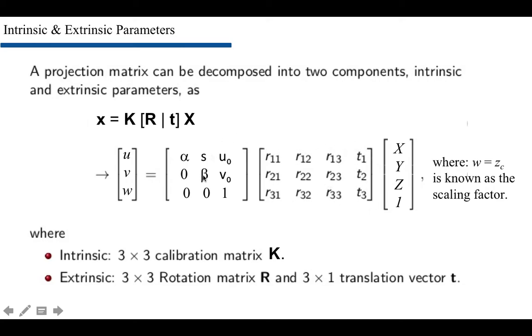But if we're doing some kind of experiment, or some kind of work with robots, and we already define the world coordinate system's origin, and it remains the same, then we can simplify. We can multiply these two matrices that won't change at all, and we will get a 3 times 4 final matrix, a single matrix, and all we need to do is multiply it by the point P in our coordinates and get the vector.